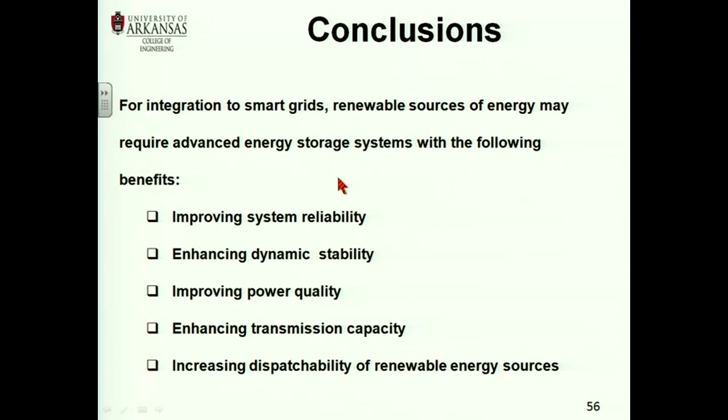Sometimes, for example, spinning reserve. Spinning reserve is when you have a generator that is rotating, that's why they call it spinning, but it's in reserve. It's not generating, or it's generating very little, 25%. Like a natural gas generator, the peaking plant in Tontitown, the peaking plant in Elkins. And so when there is a demand for more power, the generator that is rotating starts generating more.